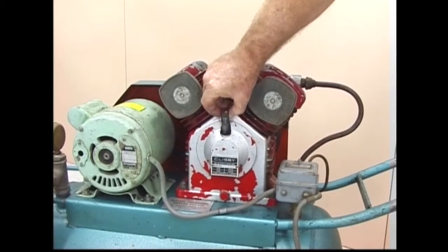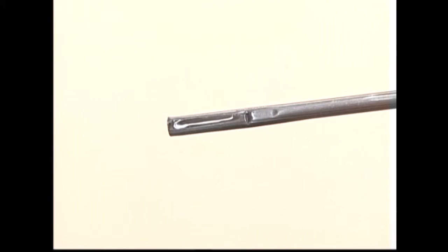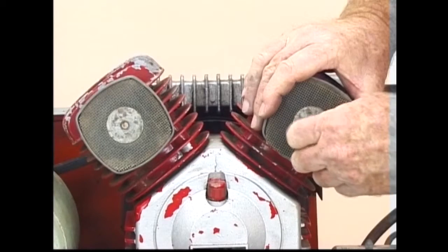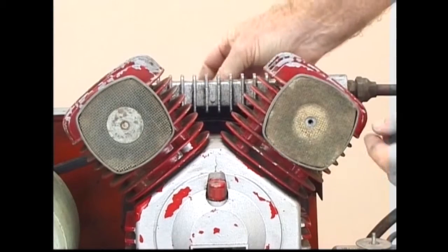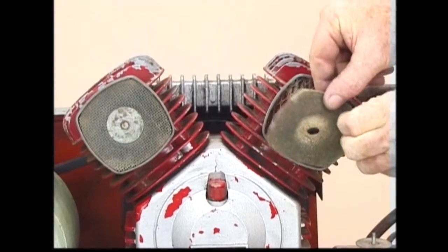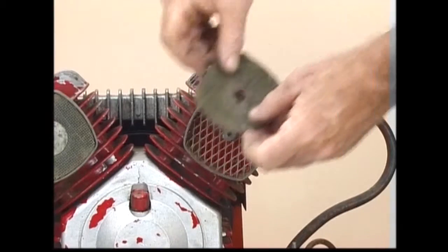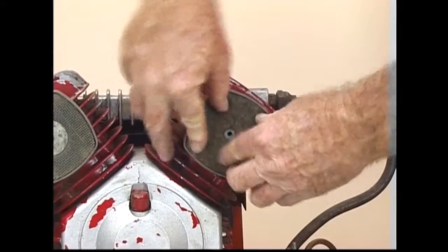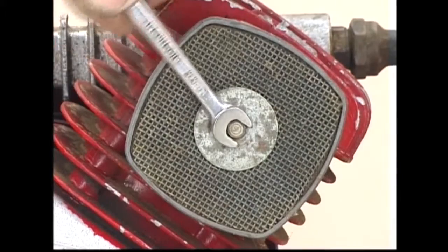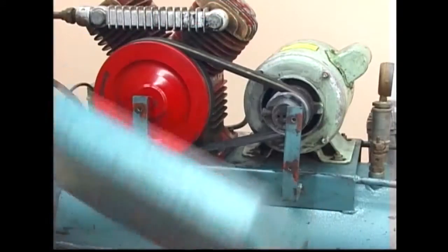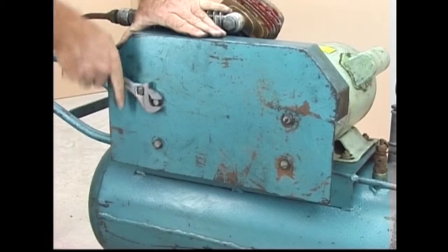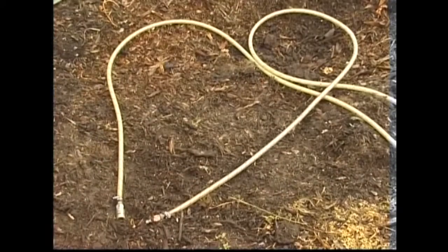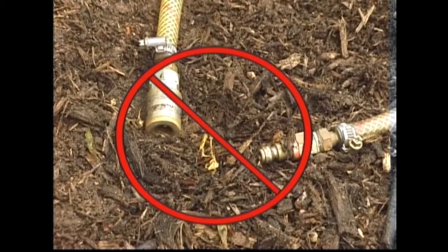If the compressor has a sump, the oil level must be checked and topped up if required. Air intake filters remove dust from the air before it is compressed. The type of filters may vary, but they must be either cleaned or replaced regularly for efficient operation. Routine checking of drive belt tension should be carried out. Air hoses and connections must be kept free of dirt and grit.